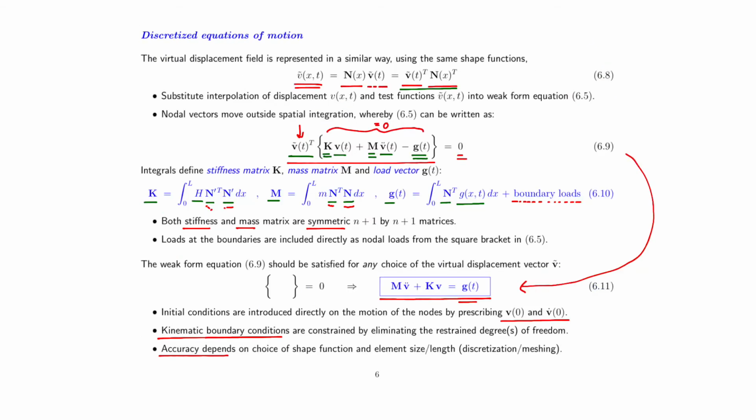So often we need some kind of discretization or meshing that is suitable in size, and we often do a so-called convergence analysis. So the idea is to find the right amount of elements to capture exactly the number of modes and the solution we're looking for. This is crucial, since too many modes and too many nodes will mean that we spend too much time on each computation, and time is money.